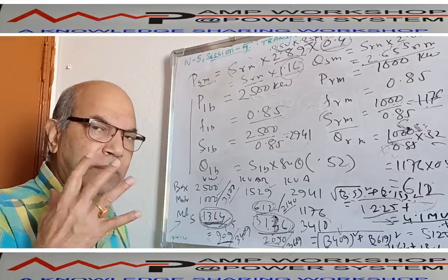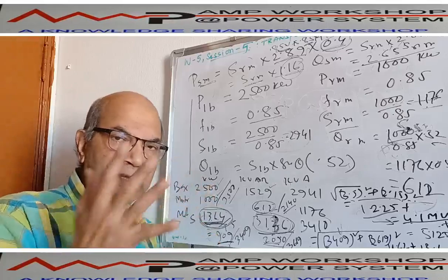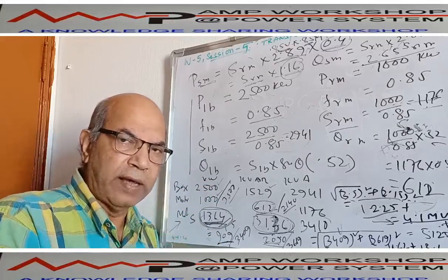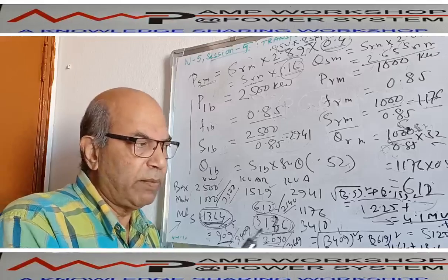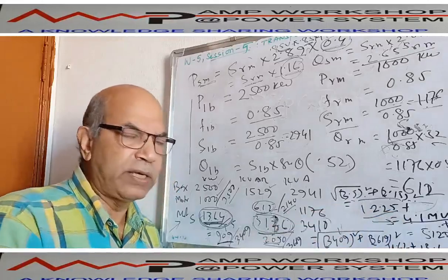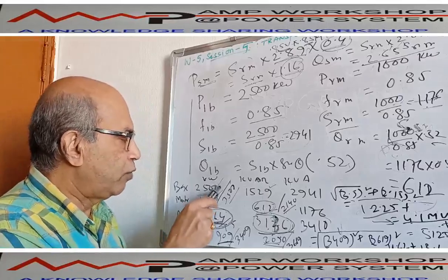And now with this we have to consider 20% as it is a continuous load, 2.5 megawatt, and the motor load, so we have to consider another 20% margin. This 20% margin we can either put over the entire transformer or we can calculate only on the 2.5.